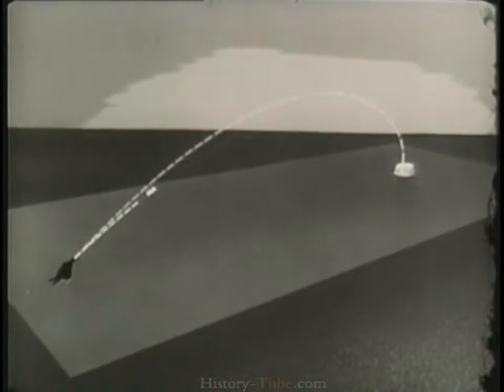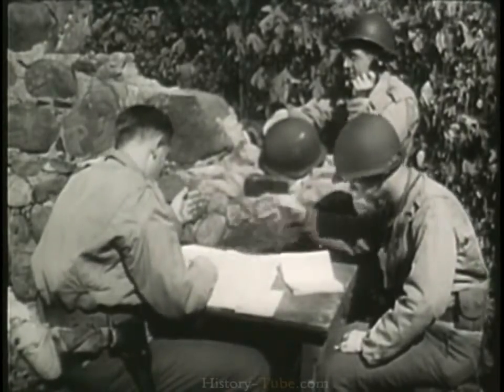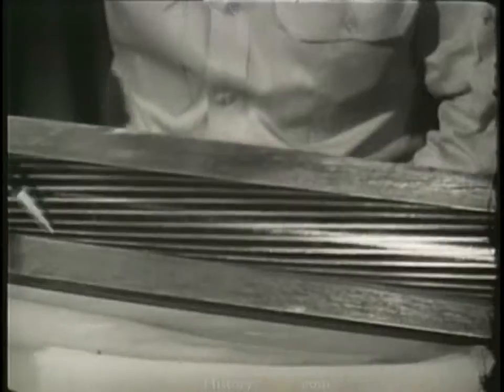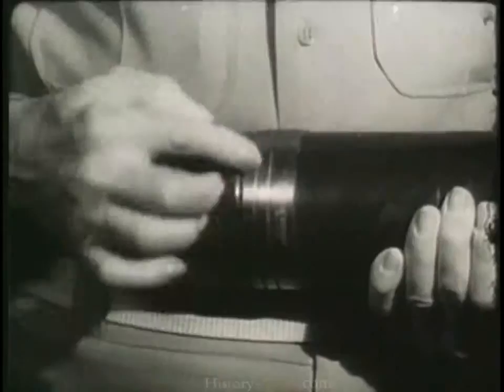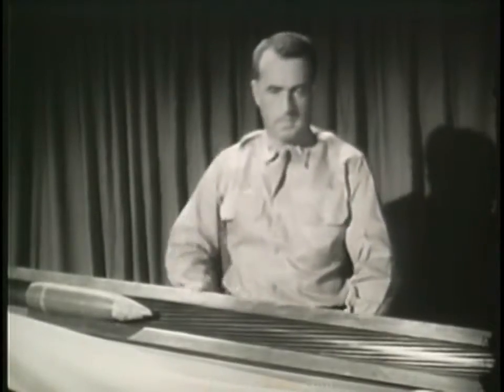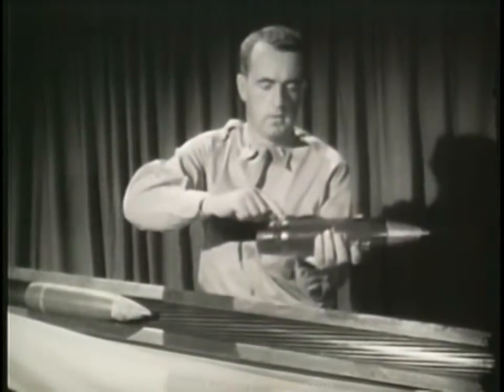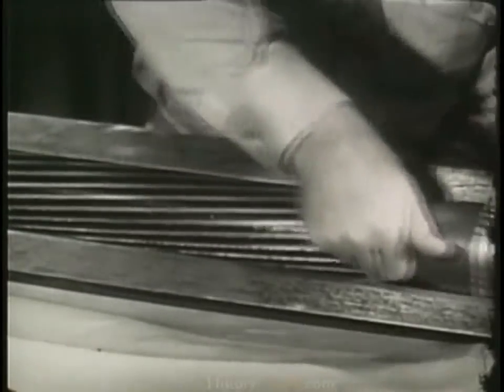This, however, causes the projectile to swerve from a straight course, drifting to one side according to the direction of the spin. That isn't as bad as it might seem because we know it's going to happen and we allow for the drift in aiming. To get the required spin, spiral grooves are cut in the bore of the gun and a soft rotating band put around the projectile. The band engages the grooves and the projectile rotates or spins.